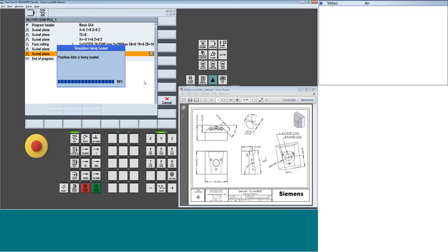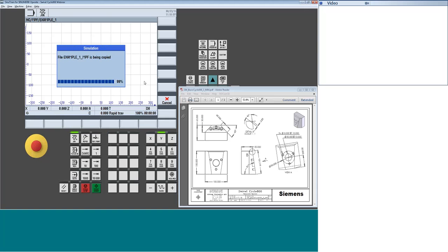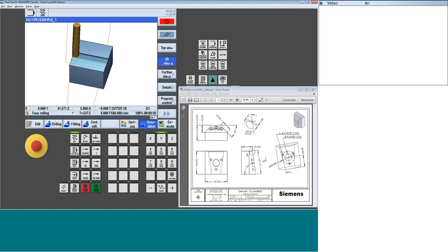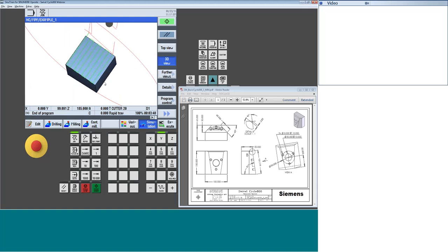in 5-axis orientation. So if I look at 3D, I see I'm now machining on a 90-degree plane. So that was that 102 mil or that 101.1 because I'm down that slope. And that is my first cut. So I look good so far. So we're now going to do really a lot of the same thing.